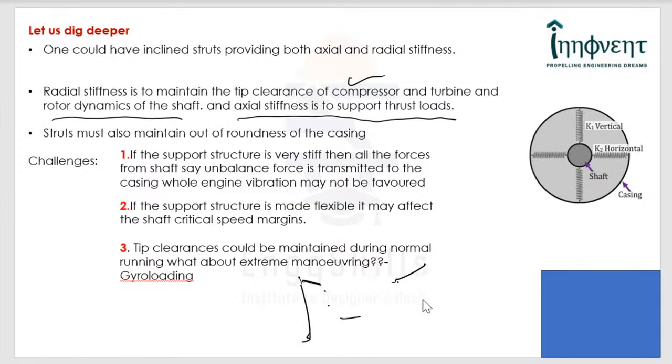in fact the pressure is increasing across the compressor, and the pressure is decreasing across the turbine, and as a consequence the thrust load on the turbine is in the rearward direction, and the thrust load on the compressor is in the forward direction, and as a consequence, there is a net thrust load which has to be supported. Now, why it becomes very, very challenging as we try to understand the system to a greater extent.